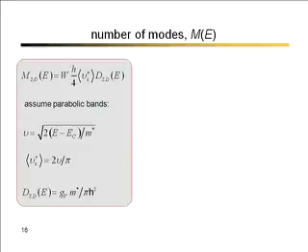As Professor Dada mentioned, these electrons are coming in and they have a distribution of angles. What's important is their average velocity in the direction of the channel. So if you do that averaging over angle, you pick up a 2/pi. And the 2D density of states, as Professor Dada mentioned, the density of states in 3D is proportional to the volume. In 2D, it's proportional to the area. In 1D, it's proportional to the length of the conductor.